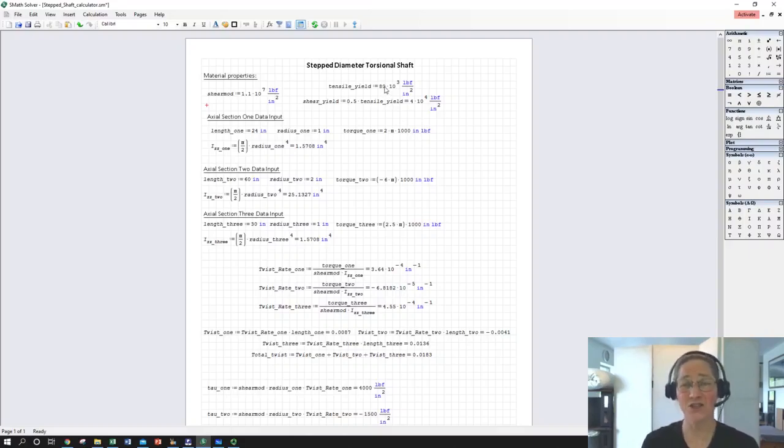but because the shaft, depending on the bearings that it's riding in, may require some wear resistance, I picked 80 just as a middle number, and so that's 80 ksi. Notice we're 3 orders of magnitude different from the modulus, which is kind of what we would expect. So in the SI system, you get your strengths in like megapascals, moduli in gigapascals. So now we have basically 10 to the 6 pounds per square inch versus 10 to the 3rd pounds per square inch.